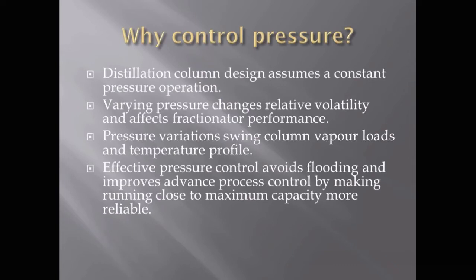The first question which comes to one's mind is, why should we control pressure of a distillation column? The issue is very simple. When you design a distillation column, we assume constant pressure, and varying the pressure will change the relative volatility and will affect the fractionator performance. And this will swing the column vapor loads and temperature profile like hell. Effective pressure control avoids upsets of the column and improves advanced process control, thus making running close to maximum capacity possible and more reliable.